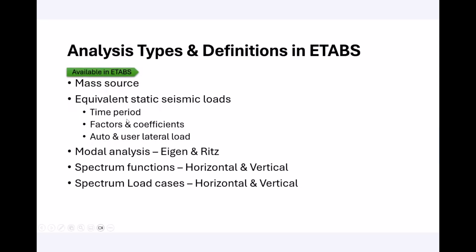Or you can ask the program to calculate the time period based on your model. That would be based on a modal analysis. So the program will use the respective time period for that direction, which has the maximum participation factor. So that's how it identifies the time period for the building.